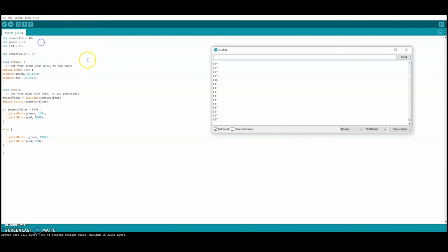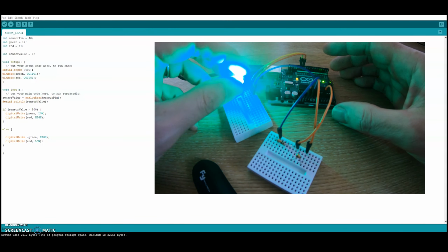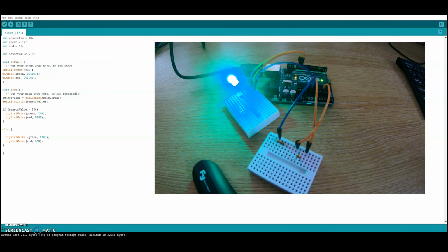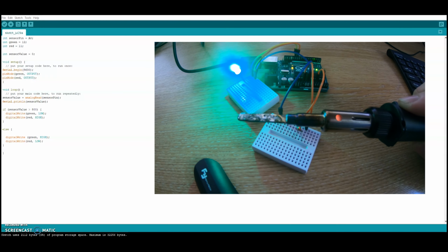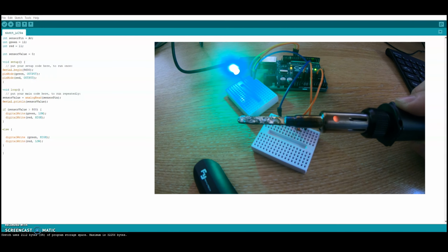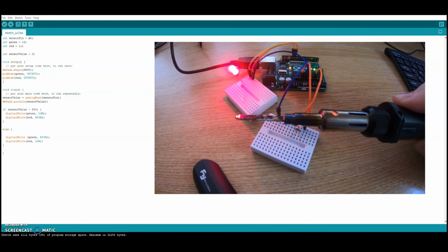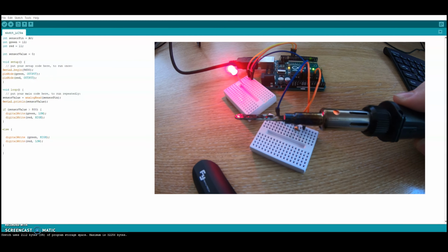Okay, so serial monitor. So we're at 536 here. You can see on the video of our circuit that we are currently showing as green, which means that it's perfectly safe. So if I take this up to over 800, so let's do that with a soldering iron. So let's bring my camera back slightly so I don't melt it. If it goes over 800, it goes red. So you can see it climbing, 900.